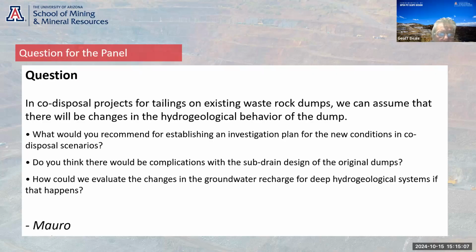There's a lot of precedent for putting filtered tailings or high solids tailings onto a dump, but not so much precedent for putting low solids tailings onto a dump. Or if there is, they're lined. So I'm not sure whether the situation you've got is for high solids or low solids.